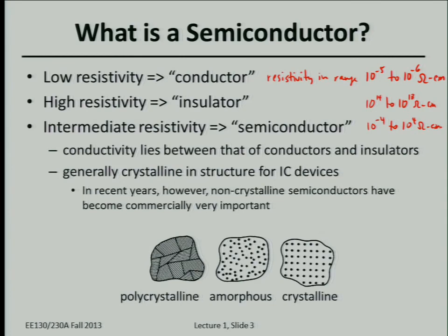Clock speeds, gigahertz, that's a clock speed, but the transistors operate much faster than the clock speed. So talking about less than a picosecond, electrons have to move around and turn on and off a transistor within a picosecond. For thin film, flat panel displays, even up to a microsecond might be good enough. In other words, electrons don't have to move around so fast for displays, so that's why you can afford to make really cheap transistors.